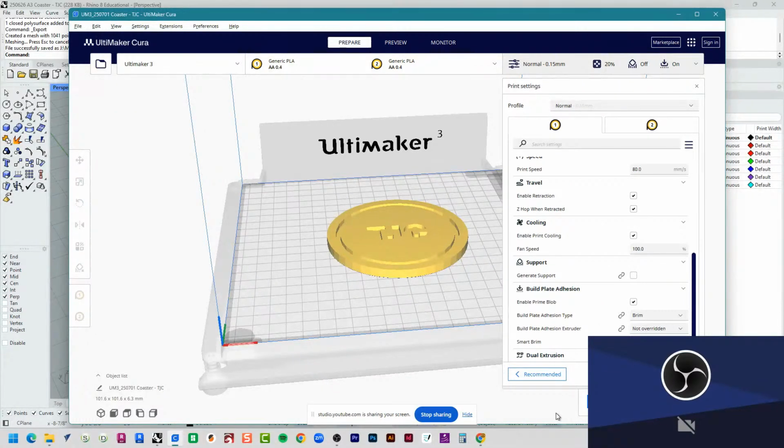Initial adhesion is super important for your 3D prints, which is why when you go to 3D print, you're going to watch that very first layer go down. And you want to make sure that it goes down. If it does not go down and it just starts pooping filament out of the extruder up in the air, you're going to know to cancel that so that way you don't waste your filament.